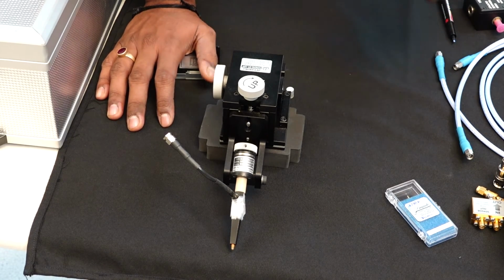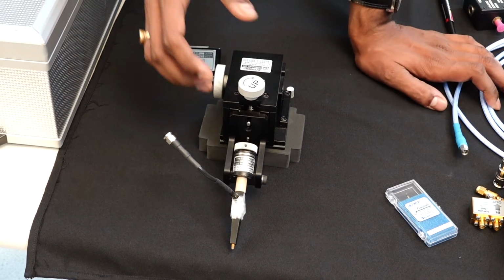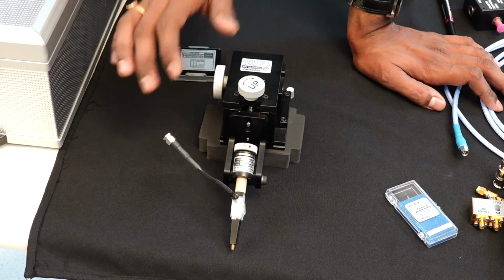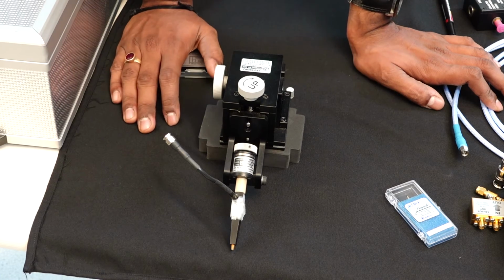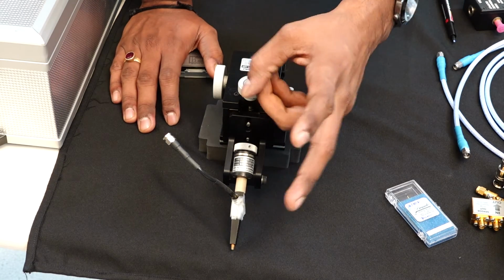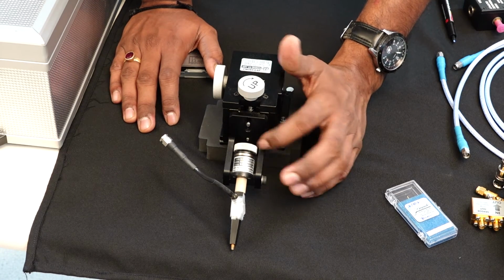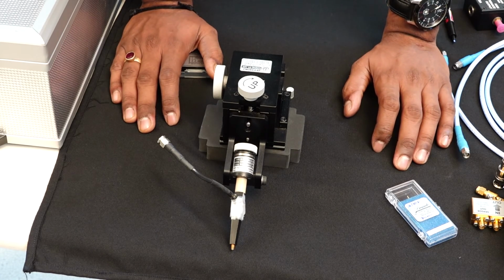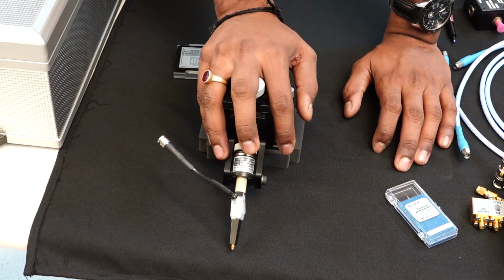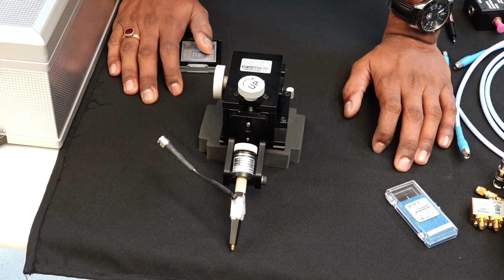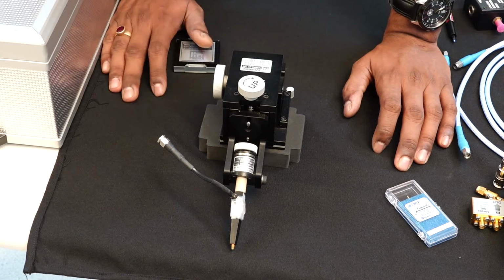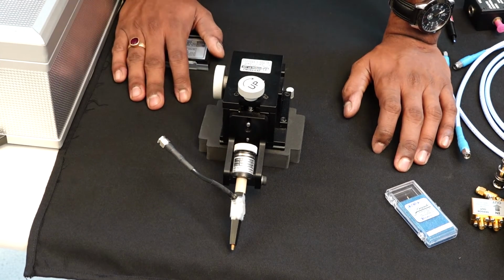For this reason, there's another control that we have in these probe arms. This is called a theta control. Basically what it does is, say for example, if your probe tip is skewed on one side, you can control this and bring the probe wires to the same plane. So this is a very typical probe arm that we use in our measurements. We have another set of probe arms as well with a slightly different configuration for SMU measurements, but for TLP this is the typical probe arm that we use.